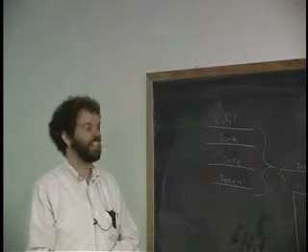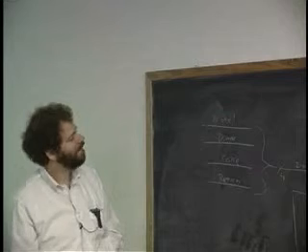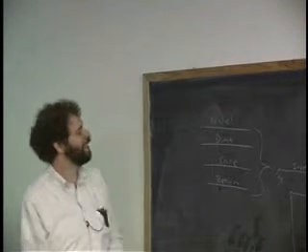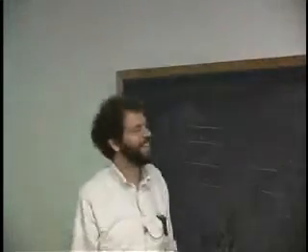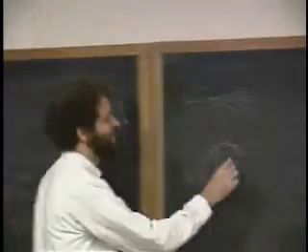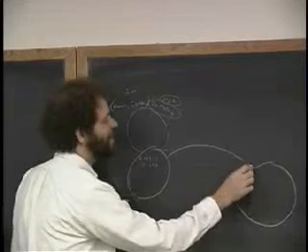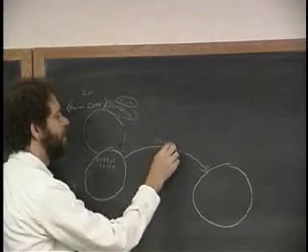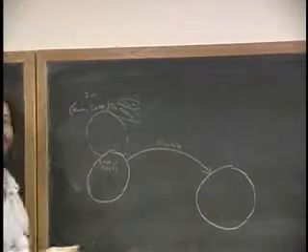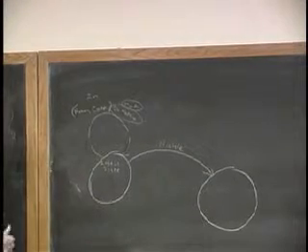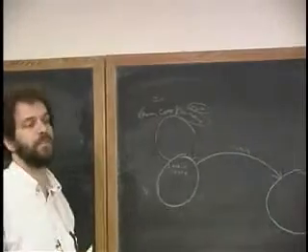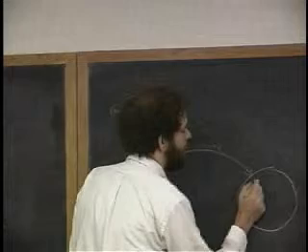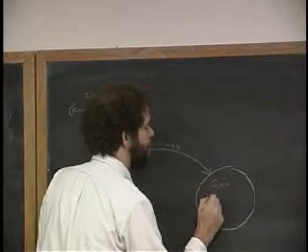But let's say that we're at Harvard, where the students actually are good at money, and they insist that the Coke machines be fair. Clearly what we want to do is if the nickel input comes in, then we want to remember it. We want to be a different Coke machine than we were before the nickel came in, and we want to change state. And I'm going to label this state, I got 5 cents. And I will remember that I have 5 cents, which is good.